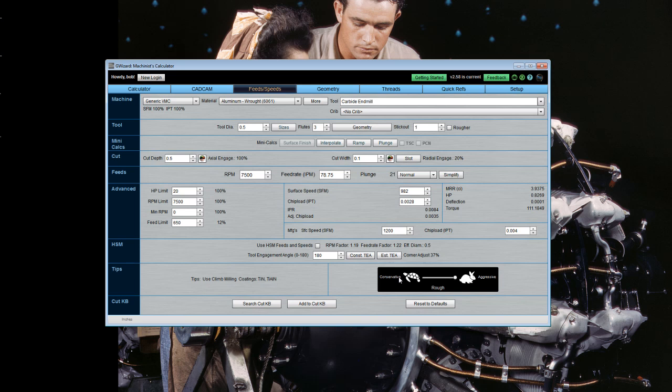Now, experienced machinists know that if you go too slowly on these things, your tool will eventually rub. So, for example, if I set the feed rate way, way low, as a beginner, I may think that I'm babying this cutter, but in fact, the chip load's too low. This may cause rubbing, and that will burn up a tool really quickly because when it starts to rub, it quits cutting the chips cleanly, starts to generate a lot of heat, and that's just very bad for your tooling. So keep an eye out for those kind of warnings, and you saw how it turned red and so forth to really let you know there was a problem.